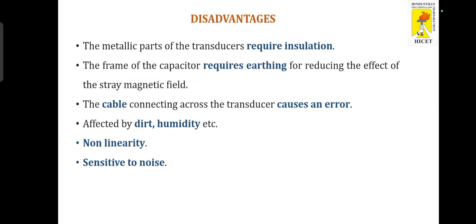Coming to the disadvantages, it requires insulation for all the metallic parts. It requires earthing. The cable connecting across the transducer can also cause an error in the measurement of capacitance. It is affected by dirt and humidity. It is non-linear and it is sensitive to noise.